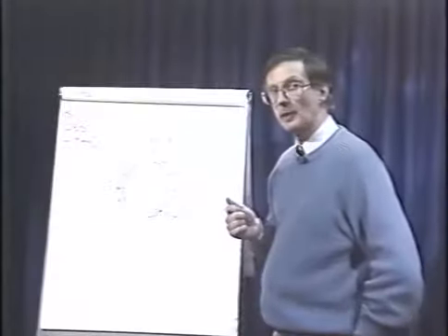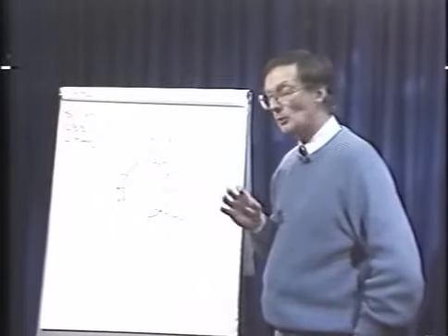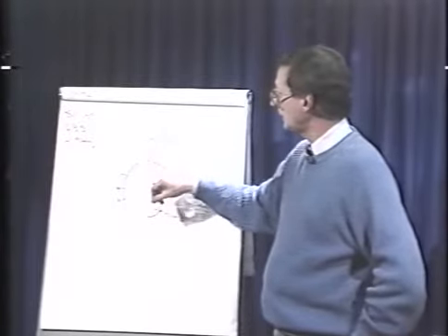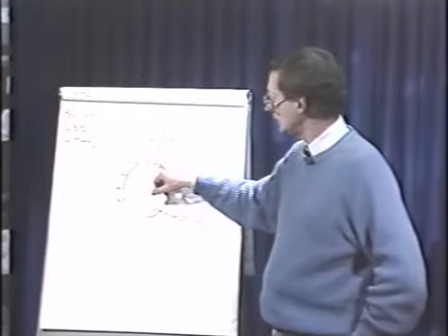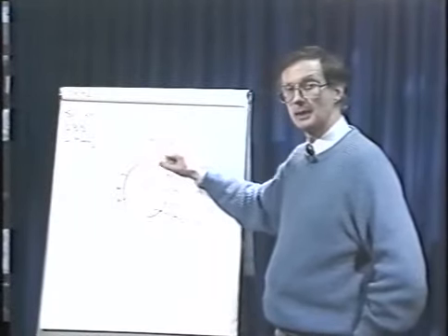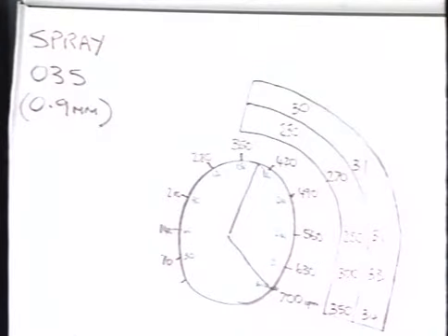The selection of parameters for spray transfer is relatively simple. Do you remember with the 035 wire where we finished the short circuit welding at the 1 o'clock position, around 200 amps? Well, to get spray and to get into that high deposition process, we have to be over 200 amps. As you can see, therefore, the spray range with an 035 wire is between the 1 o'clock position and between the 3, 4, 5 o'clock position.